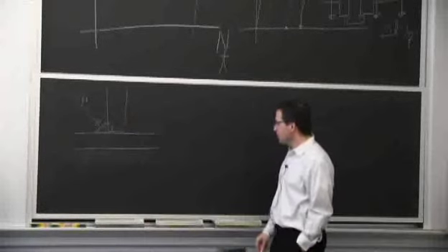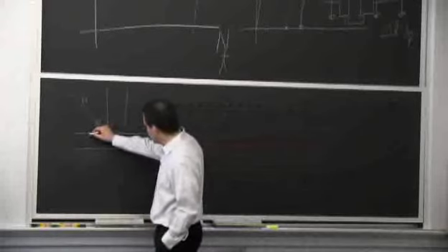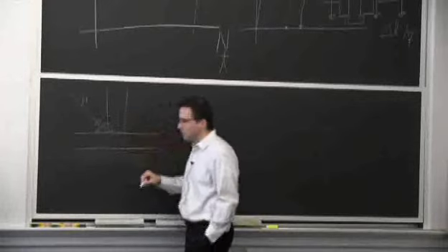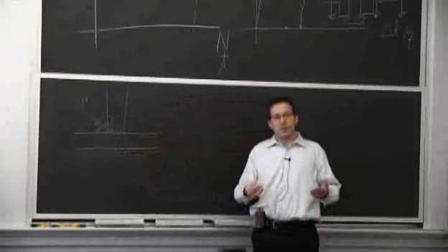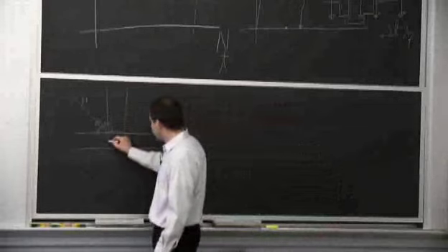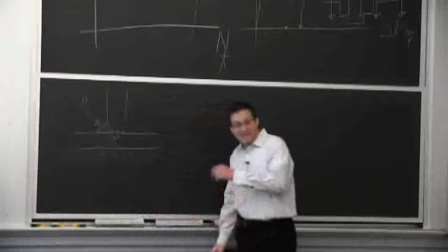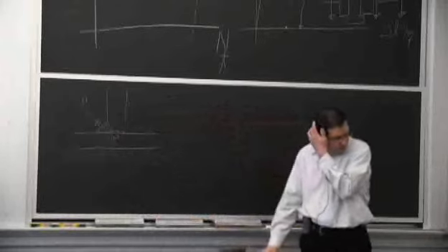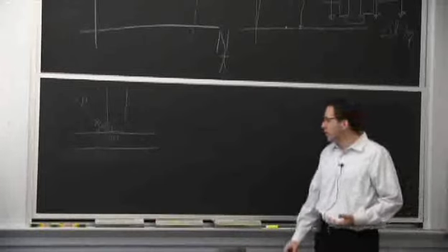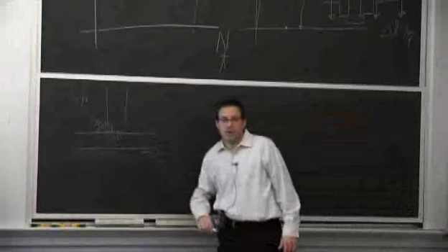Now, we will see today that there's an area around the weld that never gets melted, but gets heated quite a bit and cooled down fast. And that one we'll call the heat affected zone. For steels, if it's a good quality weldable steel, normally the heat affected zone will have a relatively good strength.